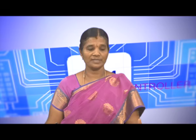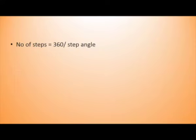So, here how are we identifying the number of steps? One complete circle is 360 degrees divided by the step angle, right. Suppose you want to use 4 steps of operation, what is the step angle? Step angle theta equals 360 by 4 steps. With 4 steps you get a 90 degree shift, right. Initially the motor is here, then it comes to here, then here, then here. This is 4 steps, okay, 90 degree movements.